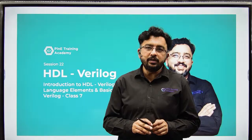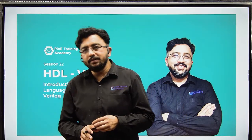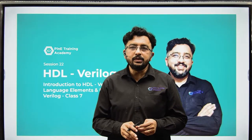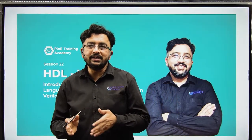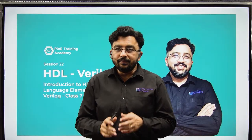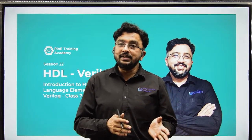But before that, let's discuss what I discussed in the last class. In the last class, I started the basic language elements used in Verilog. If you all remember, we discussed the logic values 0, 1, x, z in Verilog. Then we discussed the size, radix, and numbers, and different types of them. Suppose size is not matching with the number, or the number is not matching with the size. And if we don't have a size, then what is the default value?